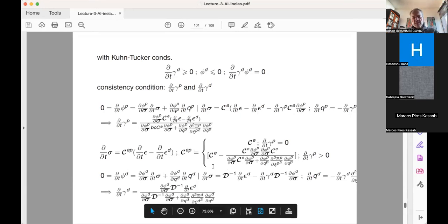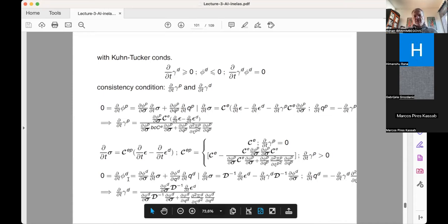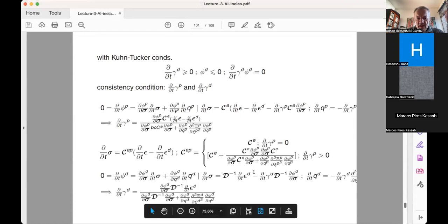In other words, if at the time t we are damaging, and if we want to keep damaging at time t plus dt, that would imply that the time derivative of the damage criteria Vd has to be equal to 0, which amounts to saying you have d phi d sigma times sigma dot plus d phi damage dq times q damage dot. So we already said that the time derivative of this one was given here.